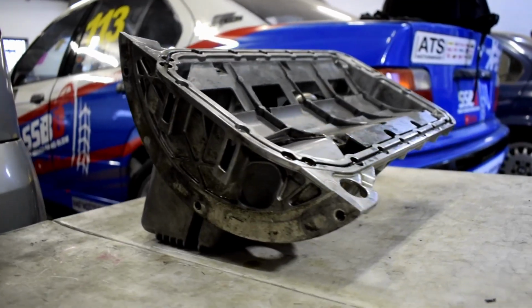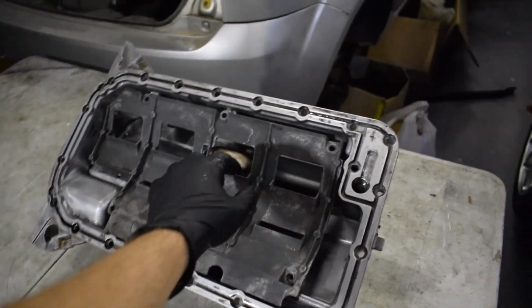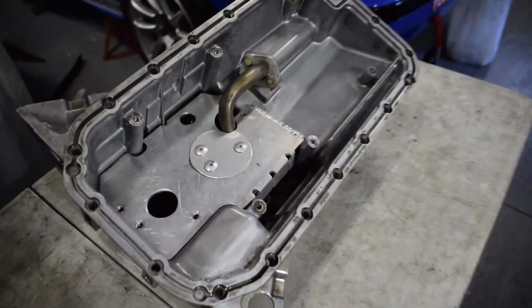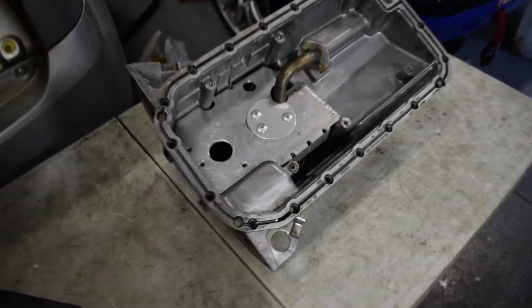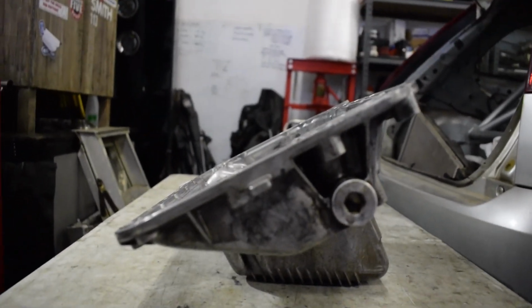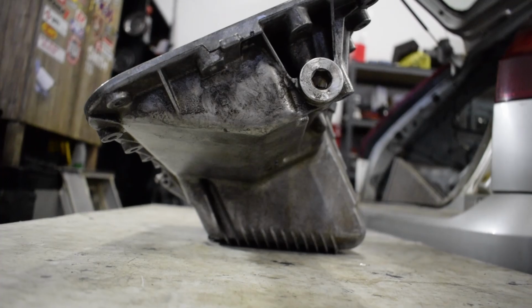So you can see from the back the position and the angle of the sump, and you can see the windage tray is there. If we take the windage tray out, you can see exactly how we've baffled the sump, right? We've got a top plate that mounts to different pickups we've put in there. You can see the angle the sump is sitting at, and the box, the pan I was talking about.